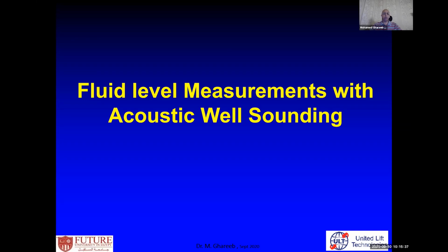I use this surface dynamometer card with information about my rod string, fluid loads, pump depth, my downhole pump size, my fluid properties, my pumping unit geometry, speed, and stroke length, all using different equations. One of the main, famous, well-known equations worldwide is the wave equation introduced by Dr. Sam Gibbs.